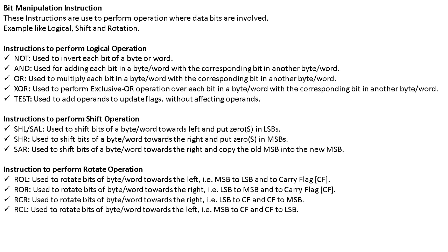SHR, used to shift bit of a byte or word towards the right and put 0. SAR, used to shift bit of a byte or word towards the right and copy the old MSB into the new MSB. Instructions to perform rotation operation.